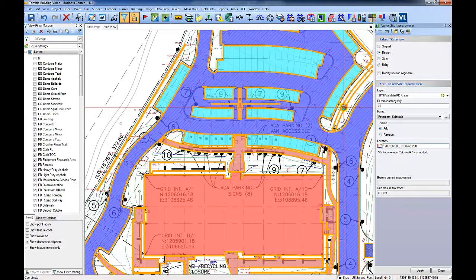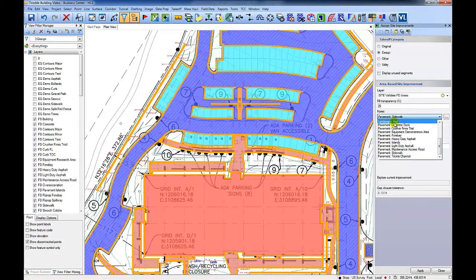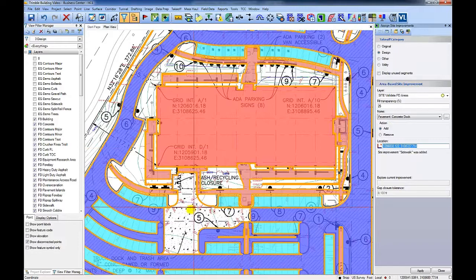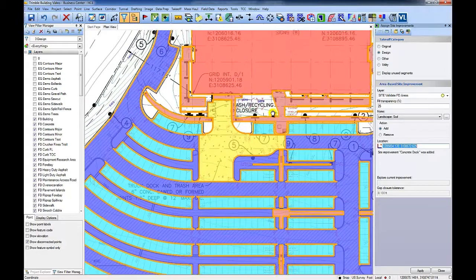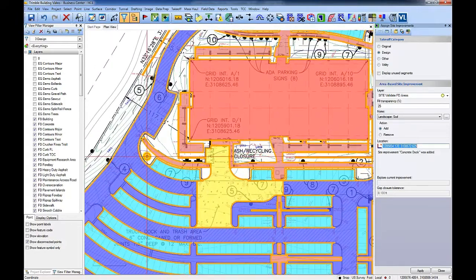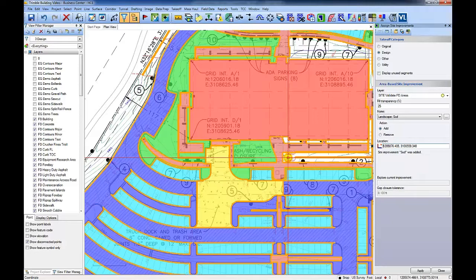You know what you have to do now to do what I'm doing. Oops, I forgot a very large concrete area by the building pad. Not a big deal. Click it, it shades. We have a loading dock that is concrete to the south of the Trimble building. Around the building, we have some grass areas that I will take off as sod. These could also be areas where you need to bring in clean topsoil to get grass to grow. I wish getting grass to grow was this easy.